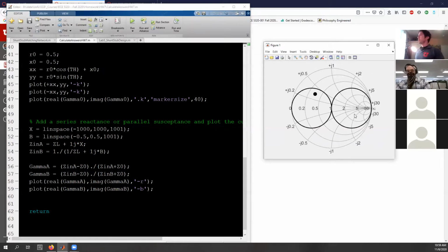Is that what the book says? Yes. And if you plot the normalized impedance, it falls inside of that circle. Right. So that's when you do high-low. If you're outside of this circle, he is saying do low-high. So that's what we said. We must do a low-high because we are outside of that circle. We've plotted the reflection coefficient, and it has landed inside of that circle.